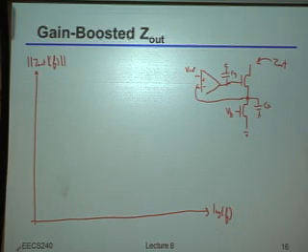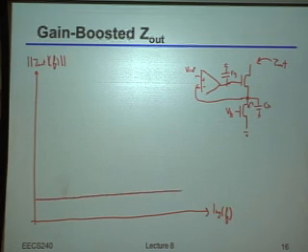So first, and again, I'm going to build this up step by step. Okay? So first, if I really just had the bare transistor with no cascoding whatsoever, okay, so I really just looked at the output impedance of that. That would just be RO, right? Nothing magic there. So that would be essentially just RO over all frequencies. Okay? Now then, if I went and I took that CX and I put it in parallel, right, then what should happen is that at some frequency, my impedance would start rolling off, right, just because of the CX.